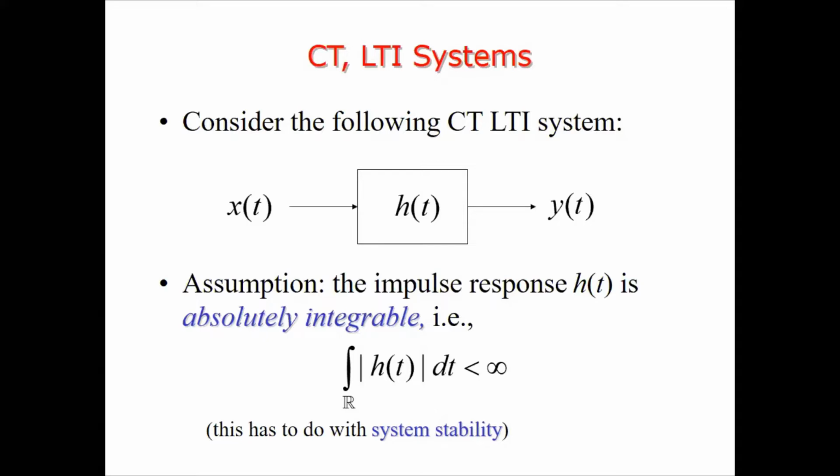Laplace of impulse function is unity. Therefore, our output is equal to the transfer function G of S when I apply an impulse signal. That's why we call the transfer function the response of the system to the impulse function, or impulse response of the system. Similar thing is true even in signals and systems.